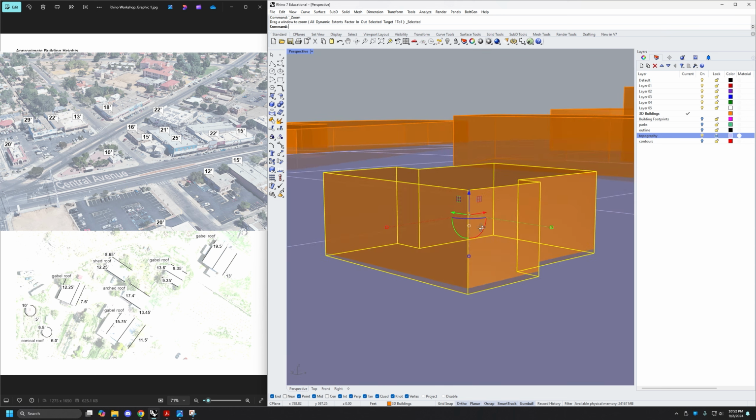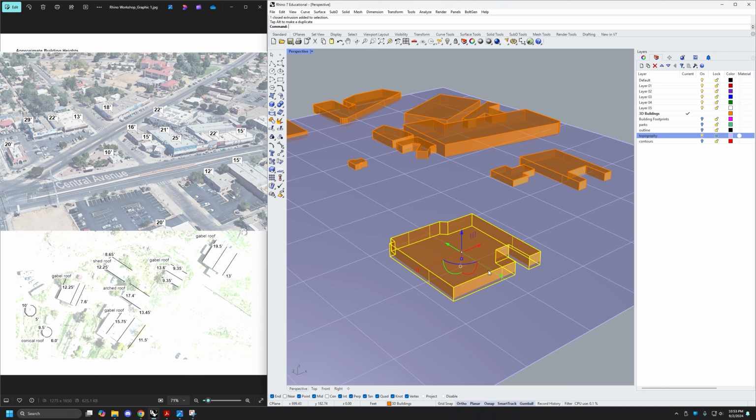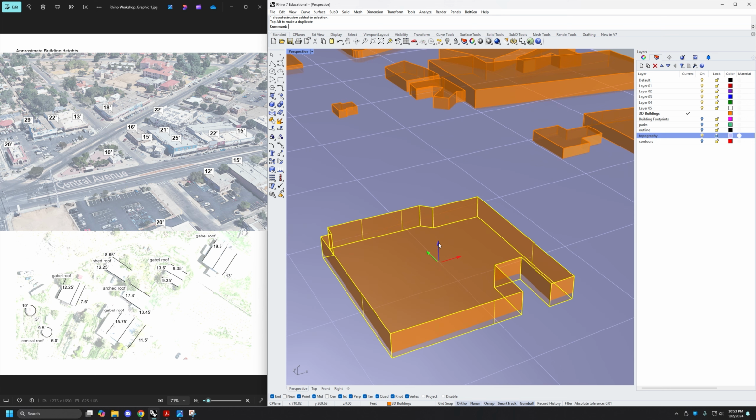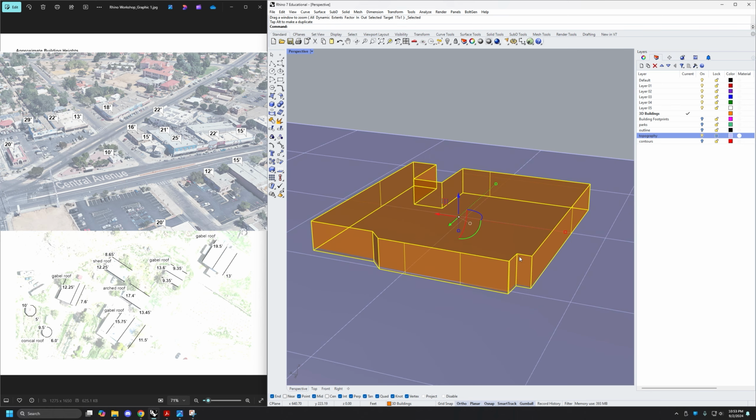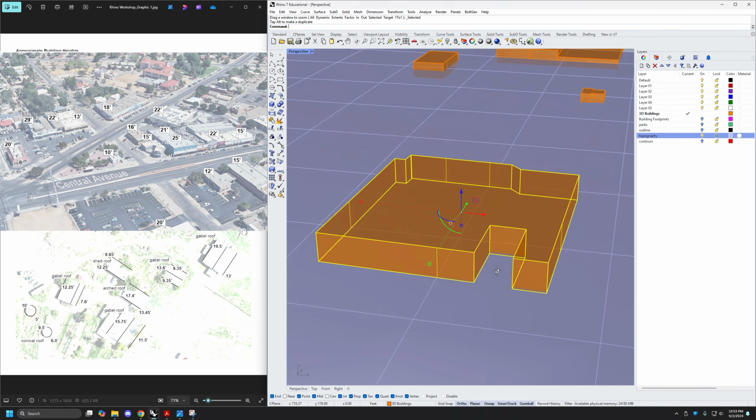using the Fabrication Labs CNC router, we would probably need a different way of attaching these buildings so that we could route out the building footprint, basically subtracting it from the topography. So we could then add a 3D printed building instead of where that outline is. The CNC router is great for creating these broad surfaces and pocketing out these building footprints. It is not the best tool for creating these buildings because the limitations of the tool just can't handle this level of detail. But it would be a great thing to then 3D print.